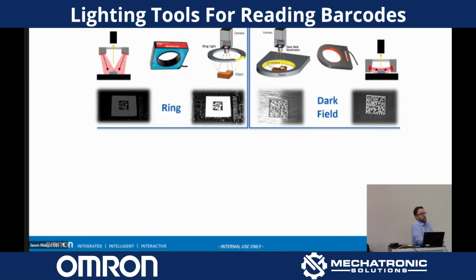Or you might get good contrast, but it's surface roughness that you're really going to look at. You're going to see more of the shape of an object than what's on the object, so what's actually printed or encoded from colors and lights. You're going to see edges significantly more than you're going to see what the actual object itself is. So depending on how you mark something, that could be a huge advantage, or that could be a huge detractor on your capability of reading.